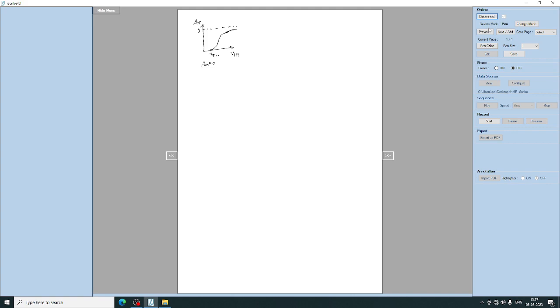As the drain current and the transconductance increase, the gain approaches 1, where you get it as GM upon GM plus GMB. If you take GM common and approximate, you will get 1 upon 1 plus eta, where eta is GMB divided by GM.